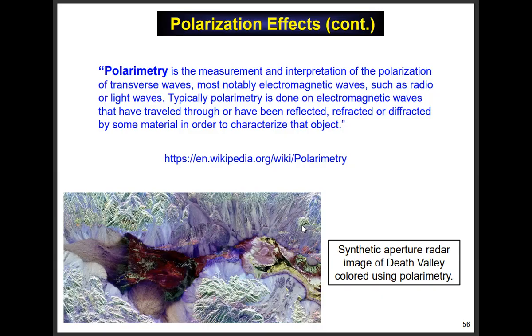It varies, but definitely the most common polarization for satellites is circular polarization, just like GPS. I'm not saying every satellite is circularly polarized. You'll find some that are linearly polarized, but the vast majority are circularly polarized, right? And that's part of the reason I mentioned the Faraday rotation effect.